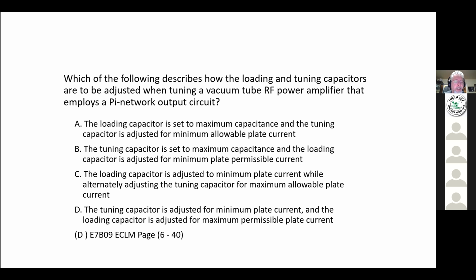Delta is correct. The tuning capacitor is adjusted for minimum plate current, and the loading capacitor is adjusted for maximum permissible plate current. D, delta.